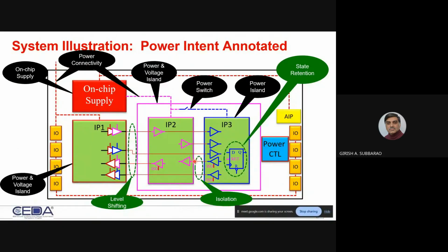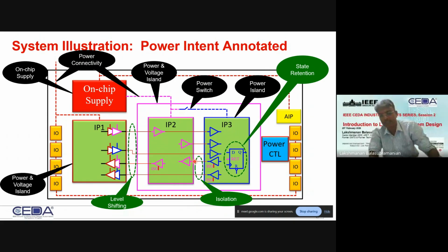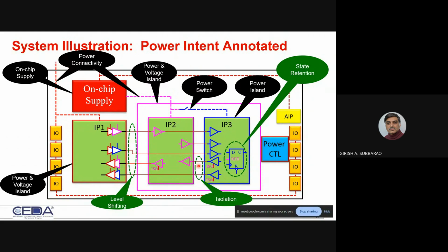But how does this isolation circuit look? It's also made of transistors. I don't know how it's actually made. It's made of transistors, but as you know, in CMOS design in general, to keep a logic 0 or 1 state you don't need a permanent current. It only charges the parasitic cap and then it keeps the state. So you're saying that using pull down resistors will be more expensive than using isolation? Expensive with respect to area. Yeah. And expensive with respect to power. Yeah.